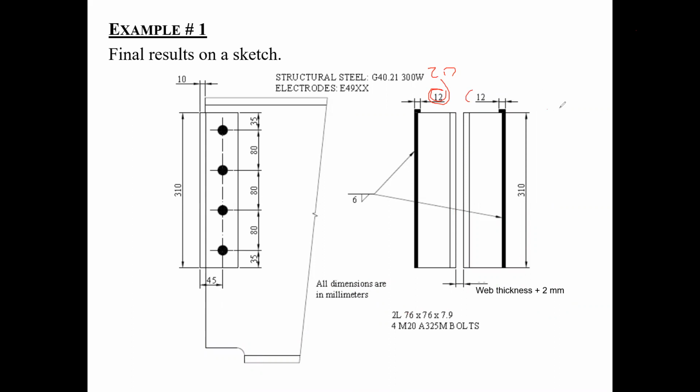So this way, the connection stays flexible, and when the beam wants to rotate, this is what happens in plan view. So here's my column. Here's my angle that's attached here. The angle actually flexes out for the rotation and it doesn't create secondary stresses because you weld it right across here, okay? I should have gotten you a picture to show you how this thing actually flexes out under its rotation. And that's it.